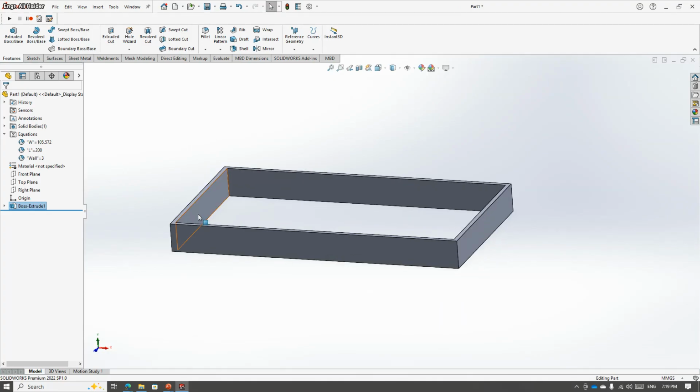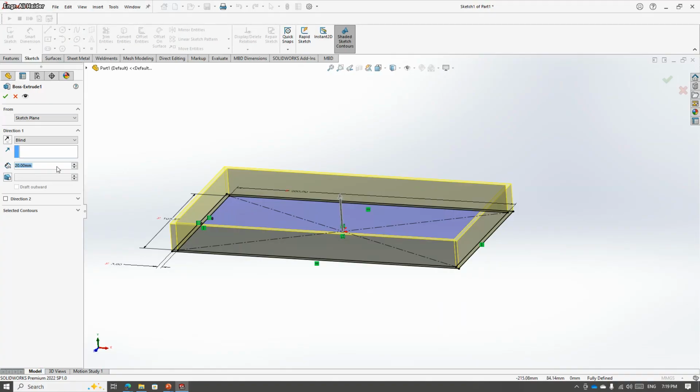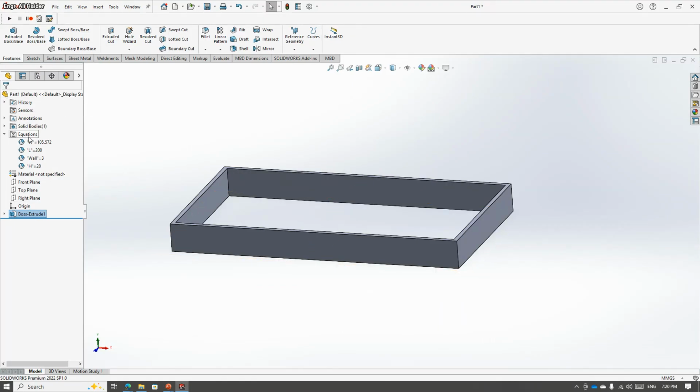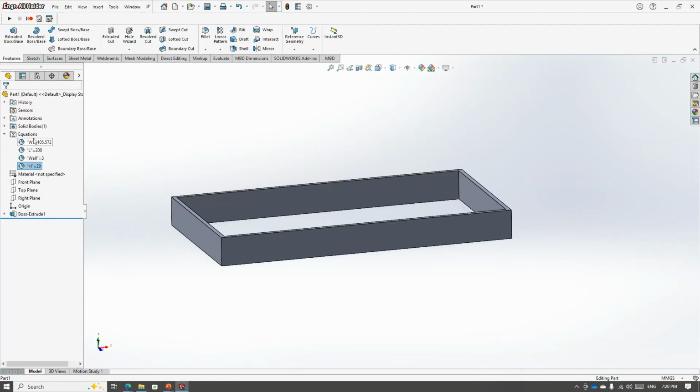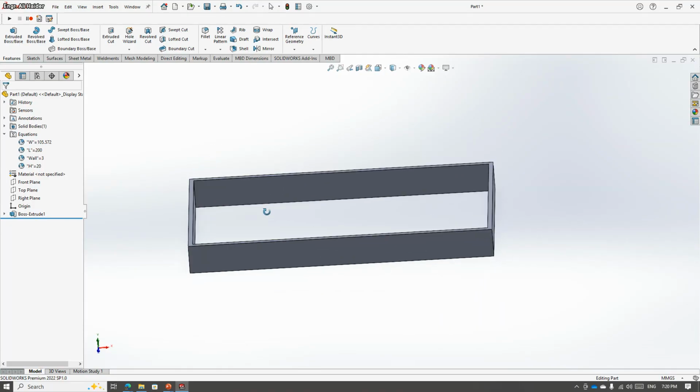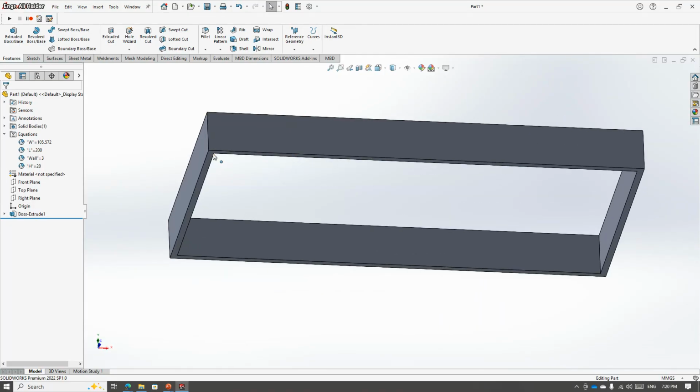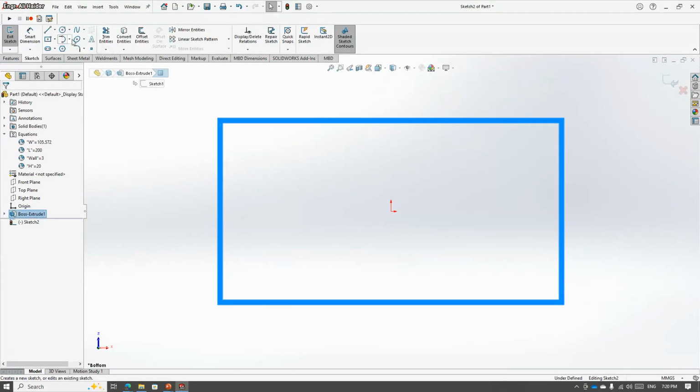Another thing there, if we want to specify the height as well, we can just simply click on equal, h for the variable, create the variable, specify the dimension of 20 mm and press on OK. So we have all those width, length and the height. And if later on we want to modify, maybe for example, if you want to add another feature, for example you have to create, let's first close it up from the bottom.